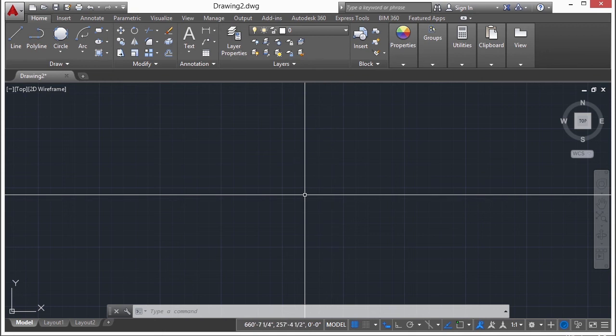In an earlier section, we discussed how AutoCAD uses a Cartesian coordinate system. Now, sometimes we need to create nodes at specific coordinates. Those are known as points. There is a command that can help you draw a point. Its size doesn't matter because a point actually has no size. It's only a marker or a node for a specific set of coordinates.